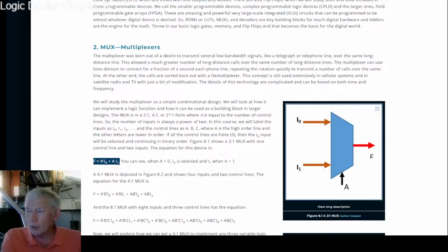But our digital multiplexers, which is all we're really going to talk about in this course, we either input a 0 or 1 and we output a 0 or 1, and there's nothing in between. So these would not work to connect wires that weren't operating in a digital mode, where they just had values of 0 and 1. If you want to have some other value connected, you don't need a digital multiplexer, you need an analog multiplexer. All right, that said, let's look at the equation for this.